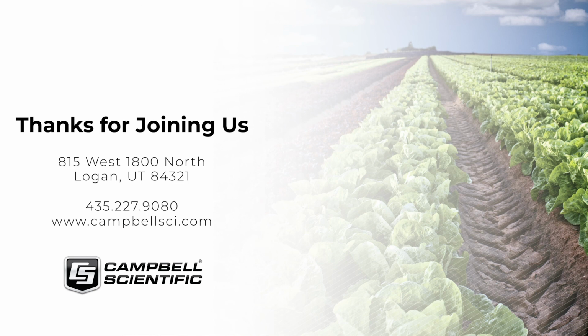And so if you're taking a point measurement and applying it to a large area, you're going to have some built-in uncertainty anyway. So this is me going around and around saying it depends. But if you need something really accurate, probably the CS616 is not your best bet. You would want something like a TDR, and that way you don't have to worry about effects of texture and electrical conductivity. And Shaw, do you want to add anything to that?